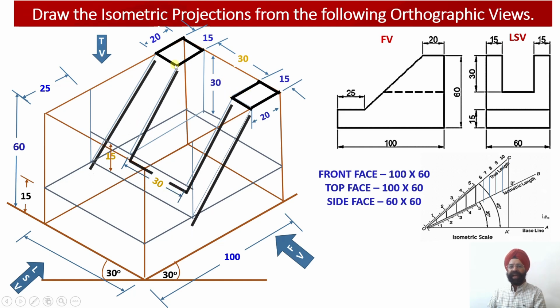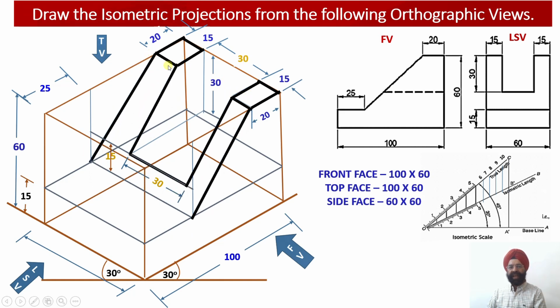Then you have the inclined webs. So this is the inclined web. Internal portion of the web is hollow. So there is 15 millimeter flat over here, there is 15 millimeter inclined surface over here, and there is 30 millimeter hollow portion over here. So all these portions have been identified and appropriately located. So this is my flat web and this is my U shape of the web.